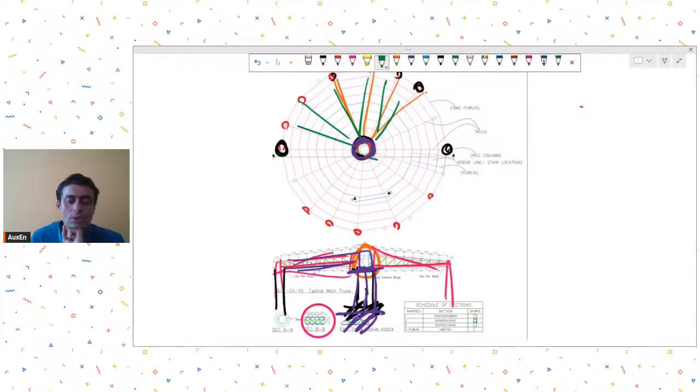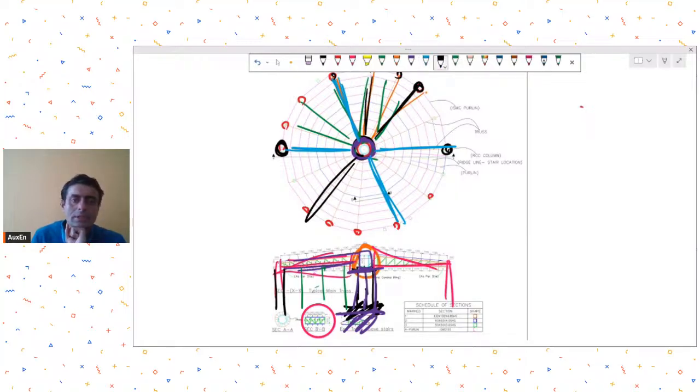And below your trusses also, initially you could place some props, although be careful with the props, because those props will add to the bending moment and it may change the behavior of the truss. So be careful with how you are putting the props on the truss. And then I think you could place these trusses diagonally. So first you place this, then you place this, then maybe you place this, you place this. So diametrically opposite trusses you can start placing. All the time this central ring is supported, and then once all these systems are in place, then maybe you can remove the prop from below.